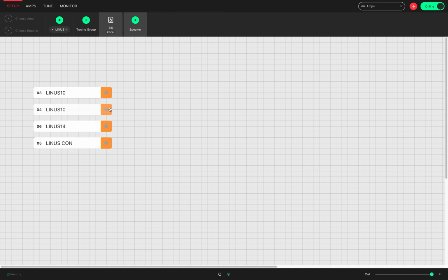The amplifiers are now accepting the analog signal, as is shown by the grey circle in the signal area. The background of the signal area is orange to get your attention. When the digital signal is reconnected to the amplifiers, a yellow ring is drawn around the grey indicator to infer that the amplifier is once again ready to accept the digital signal. A button now appears in the top toolbar which, when pressed, asks all amplifiers that are ready to revert to their digital signal to do so.